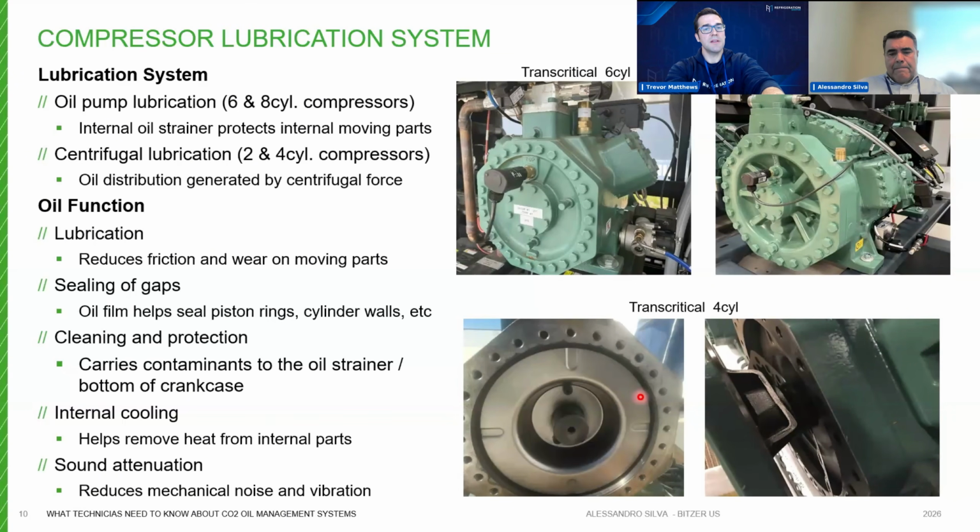So could you do a dynamic disc on an 8-cylinder? No, for large capacity it's not so easy. We need an oil pump for large capacities, when we have more moving parts on the compressor. So the oil pump is the best option. Yeah, because you've got a longer crankshaft now, with more journals for all the pistons and the rods. And with the dynamic disc, you don't have any positive displacement, right? Positive or centrifugal force is correct, to push the oil all the way through the crankshaft.